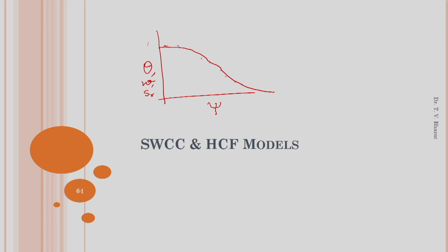because the soil water characteristic curve and hydraulic conductivity function are required input data for the flow through unsaturated soils. Therefore we require a smooth functional form between psi and theta, and k versus psi. These functions are often required for the hydraulic conductivity for flow through unsaturated soils. So we require modeling of the measured data from the laboratory or in the field.